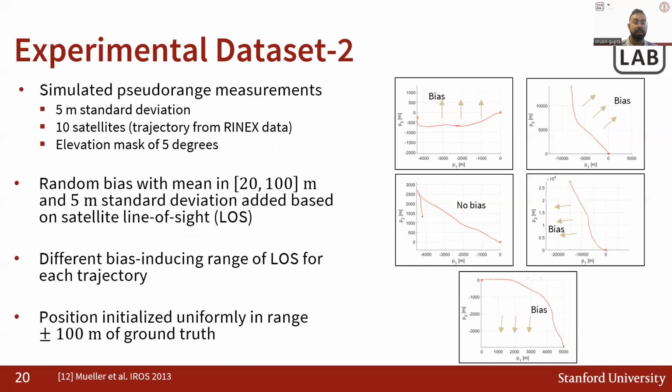The simulated data set contains pseudorange measurements, which have a 5-meter standard deviation. And we used 10 simulated satellites whose trajectory was determined using actual RINEX data. We also apply an elevation mask of 5 degrees on these satellites.